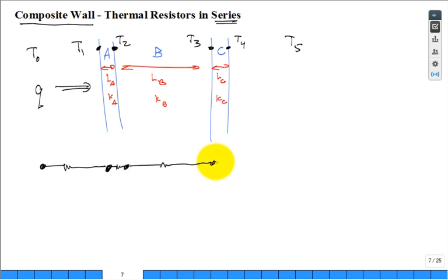Here I'm trying to line up the location of the nodes with the spatial location of the temperature at the interfaces. But this would be the node temperature T0 to temperature T1, the value of the temperature T2 at that node, T3, T4, and T5. Notice, in our equivalent thermal network, temperatures are at the nodes.